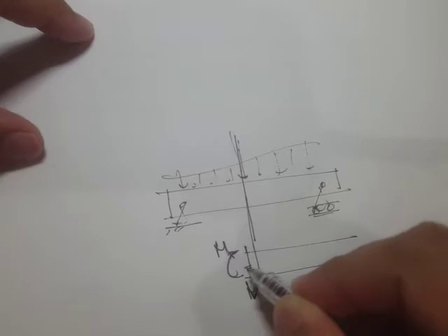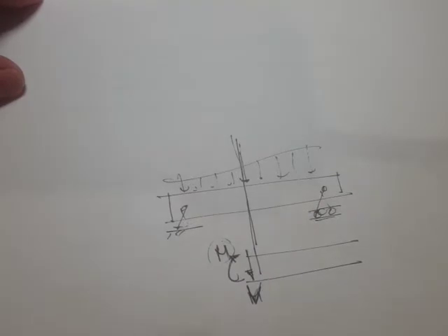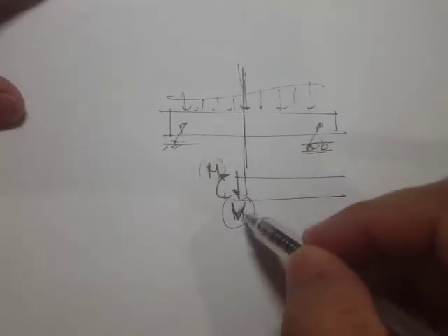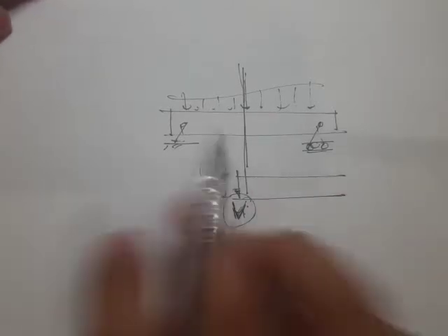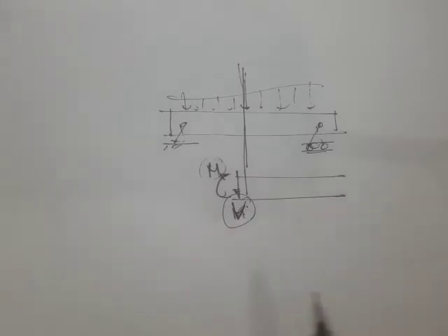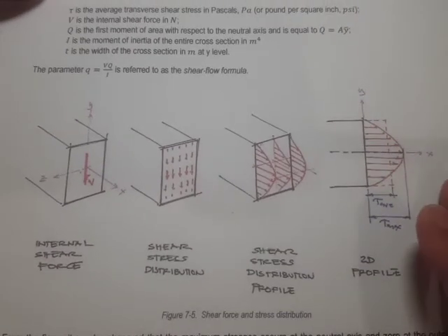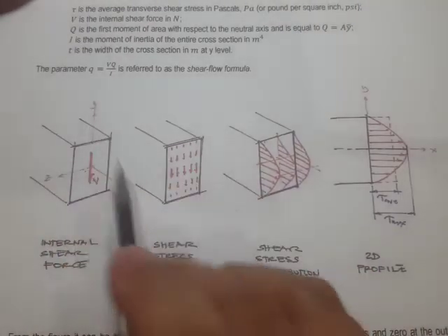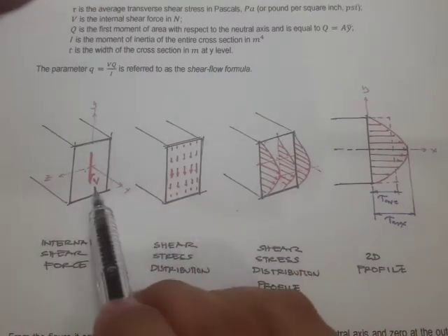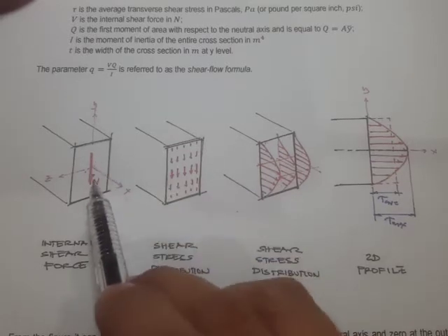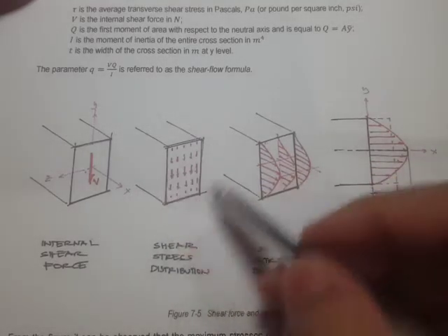Previously we calculated the moment portion for the flexural stresses, and right now we are going to solve for the shear stresses in beams, because there also exists shear stress in the internal forces. In our lecture handouts in figure 7-5, we have a section cut, and it shows the internal shear force. If we represent this resultant shear force in terms of its stress distribution, it will look something like this.